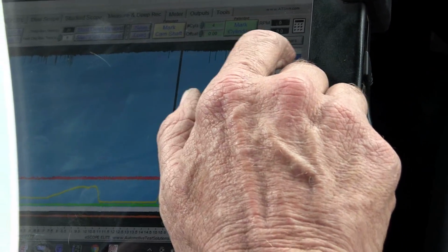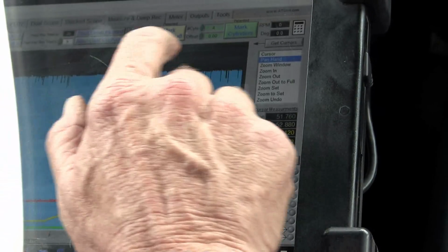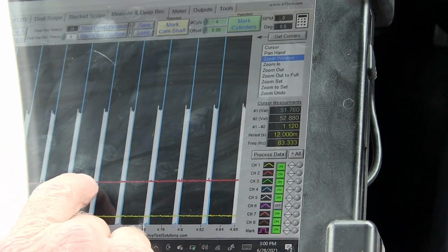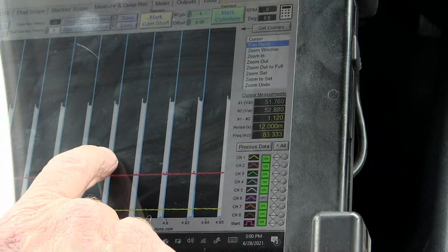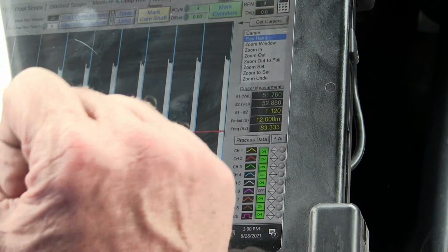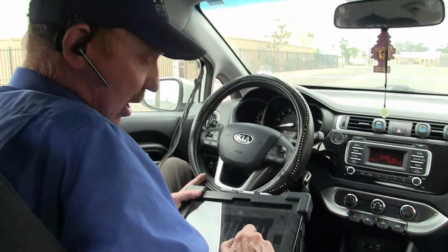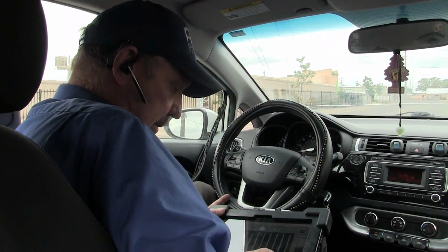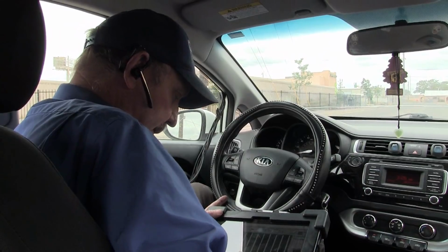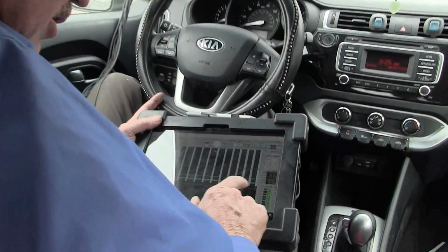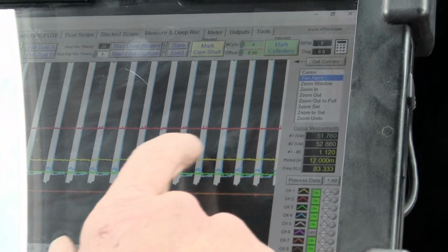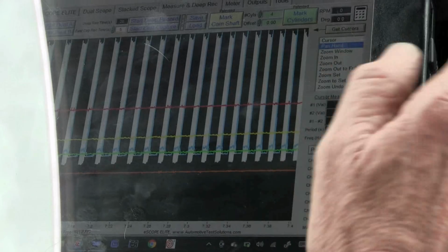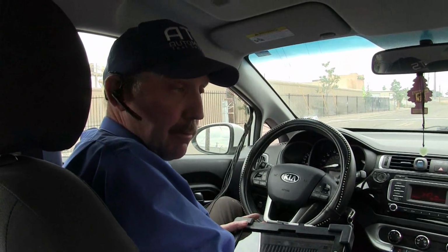And when we go back out here, and we go over here where we had, over here, we can see that these aren't on as far. These are on for a shorter period of time. As the plunger is coming up, this turns on earlier to try to get more fuel if we need more pressure. Now here we can see we're losing pressure here, and we can start to see how much wider these are coming on. The computer is trying to correct it, but it can't.